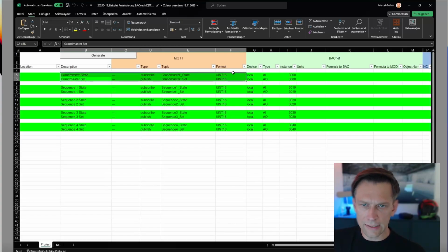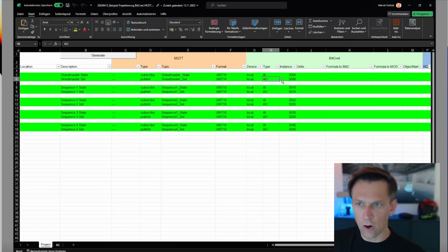Okay, and the next line is set information. So we want to publish to MQTT topic grandmaster set, and the analog output from BACnet is also on the instance 3000. Same as the sequences, so feel free to pause this video and have a look at this. Again, feel free to contact us, contact me, so I can provide you this tool. This is very helpful. Finally, you need to click on generate, and then it will generate again 3 configuration files which can be easily imported into the gateway.